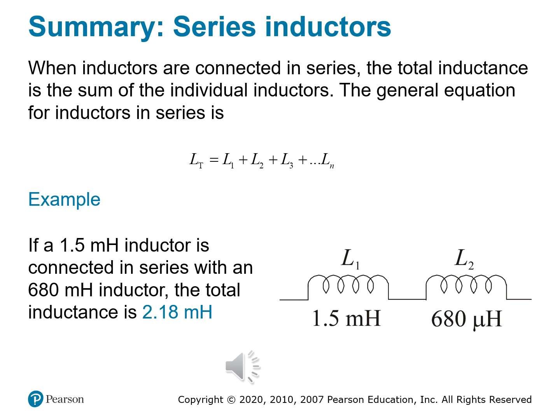So to combine different core materials, you can also do this to give you different inductances. And then let's say you want to isolate parts of a circuit magnetically while you still want to influence the current behavior. So one thing to note though is when you wire inductors closely in series, you have something called mutual inductance that may come into play. And that's when their magnetic fields interact with each other. So you may need to adjust for coupling effects. But in general, series inductance just adds up.